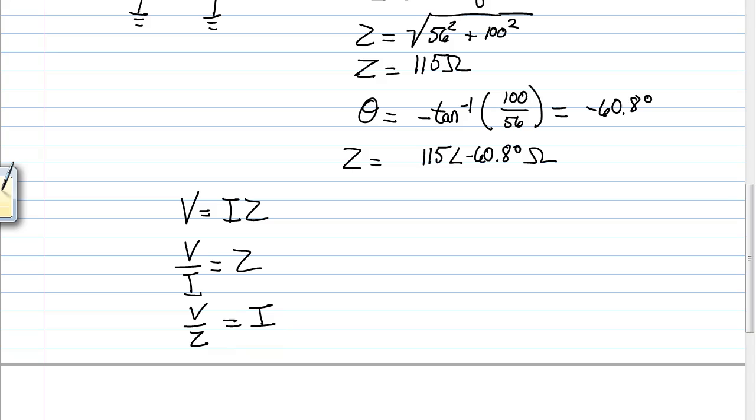Those are all valid statements. Just remember that I'm doing complex multiplication when I do this. Because I'm just doing complex multiplication and division, it's best to keep everything in polar form if you can. Polar form does really well with multiplication and division. So I would leave all that stuff in polar form unless absolutely necessary.